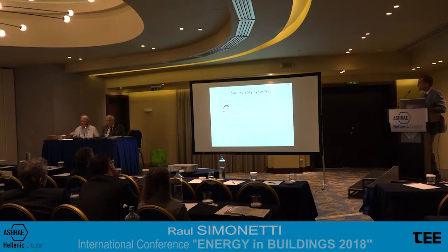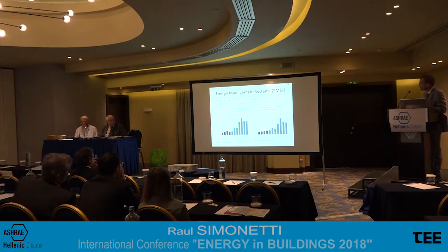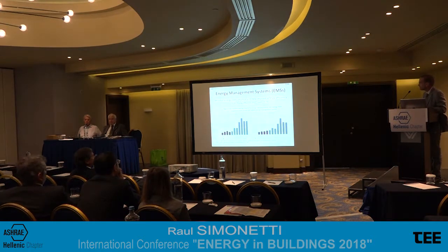Apart from these nice pictures, this is quite important. That's reported by the IEA's Energy Efficiency 2017 report. This chart shows that if you have a good monitoring system or energy consumption monitoring system, you can improve the energy saving by 3% or even up to, let's say, 12% if you have very skilled and trained personnel. So energy management systems, which are a kind of monitoring systems, allow you to keep the systems under control, make continuous monitoring, and do additional energy saving.